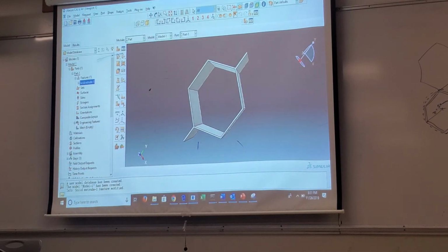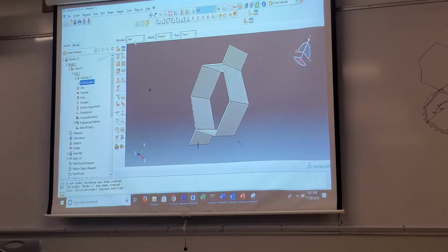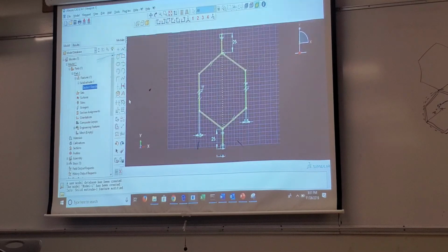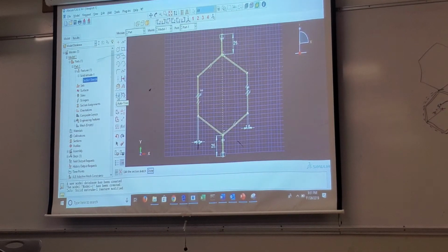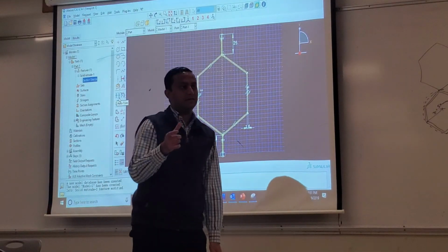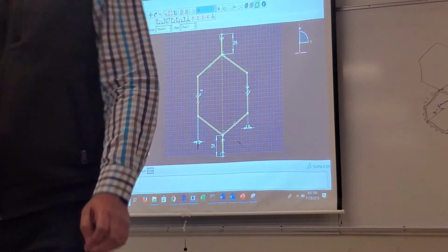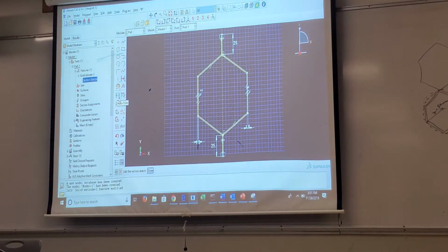Which button for the auto trim? Auto trim is, if I actually go in the sketch mode again, the auto trim part is this. Auto trim. What was the dimension of the extrusion? Height, it's 50 millimeters. This time it is 50 millimeters. You can first carry on that activity, and I will actually show you that, makes sense.